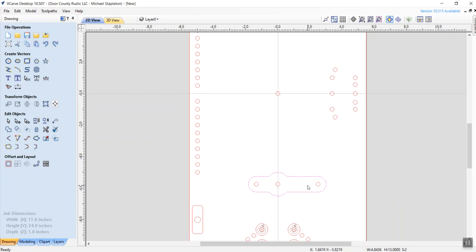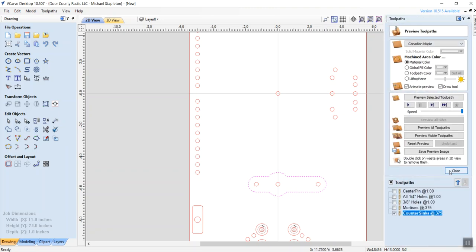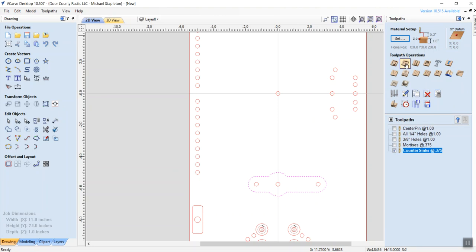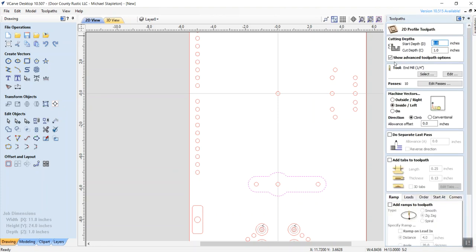Now, there's way too much meat in there to router it out, pass after pass. That's 8 passes of a lot of stuff. So instead of doing the normal, or if you want to call it normal, instead of doing a pocket toolpath, this time I'm going to use a profile toolpath. And I do want to go to 1.0.